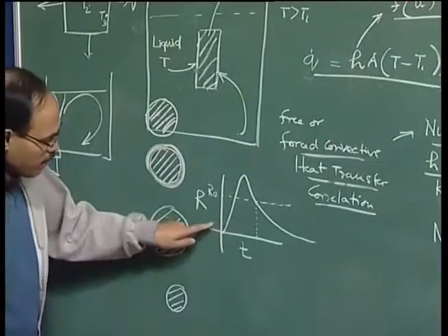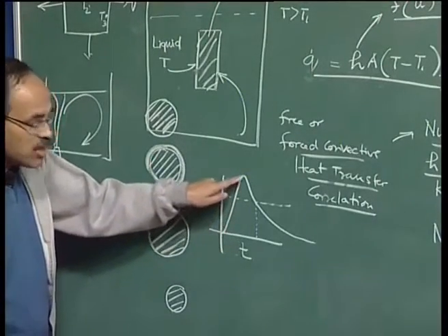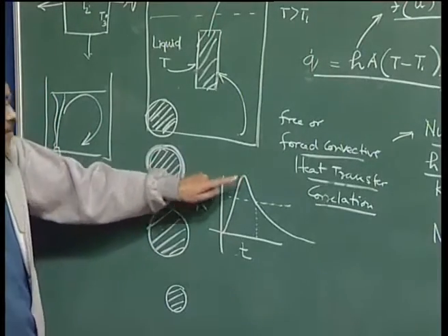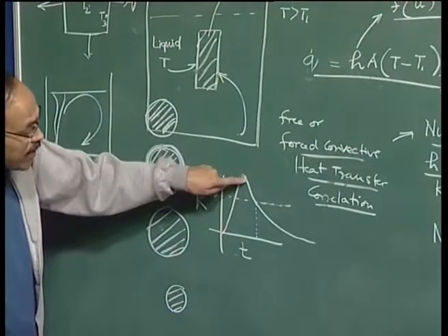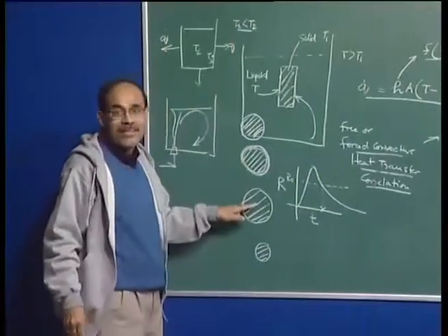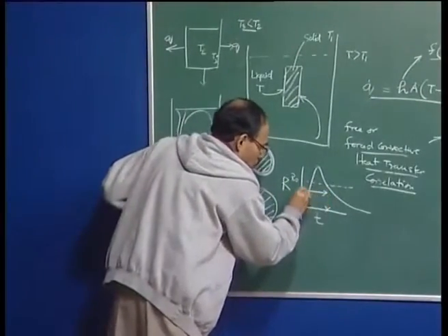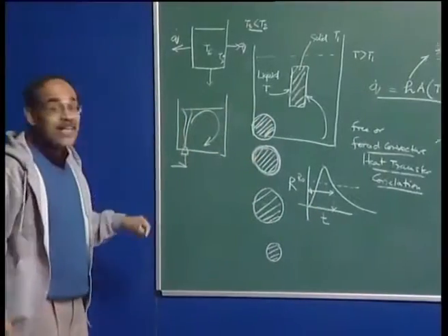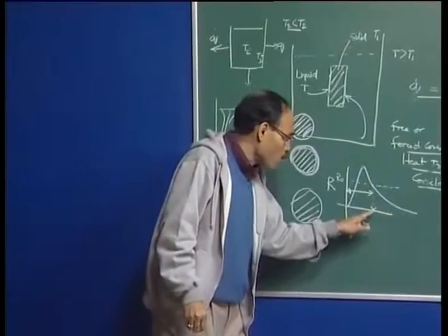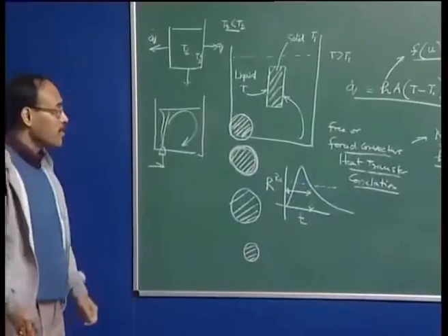So, the radius as a function of time: the radius increases, radius attains a maximum value, and at that particular point the formation of shell is complete, the shell now starts to melt back and the radius decreases, and at this particular time the original sphere is released. So, this is the duration which corresponds to shell formation and shell melt back, and this duration from this point onwards represents the melting time of the alloying addition itself.